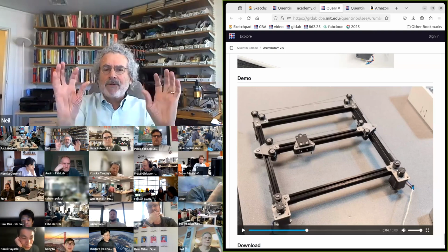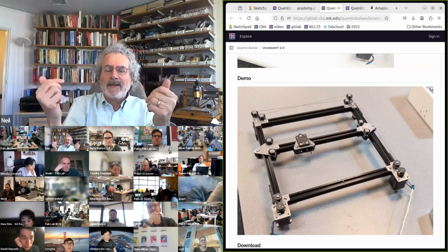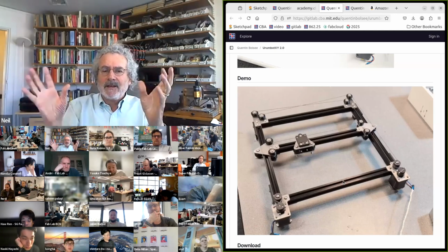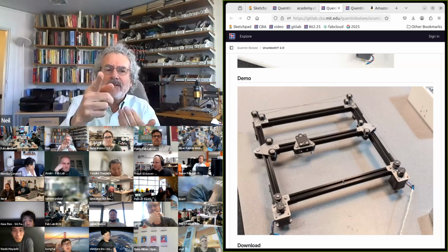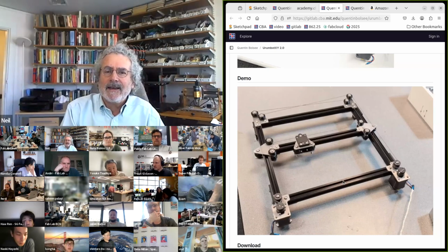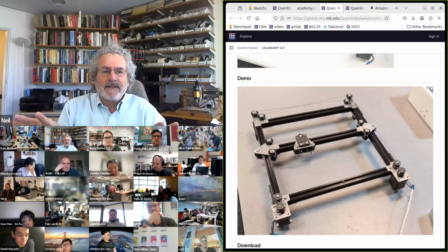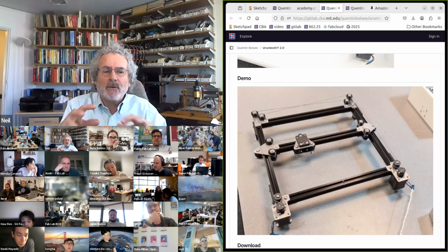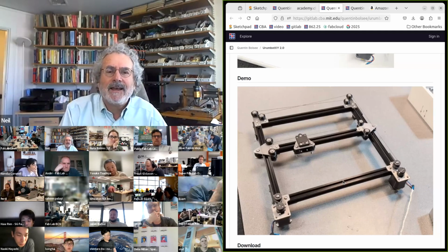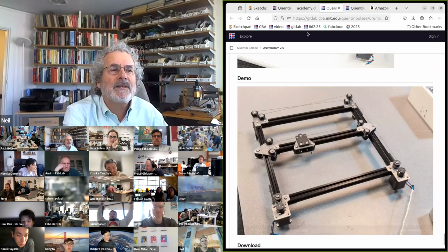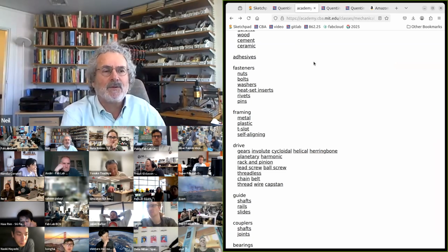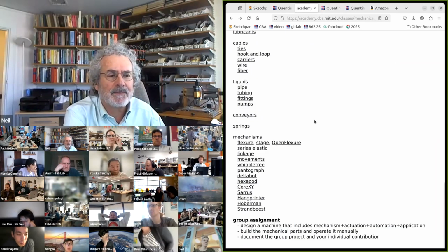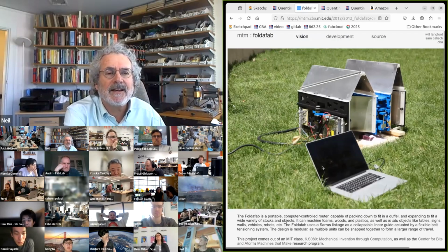If you turn both motors the same way, the stage moves in X. If you turn the motors in the opposite direction, the stage moves in Y. And so this lets you move a stage without having to move the wires or the motors. This is used in particular when you want to minimize the moving mass to move things very quickly. So that's Core XY.